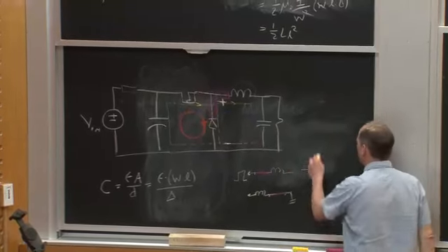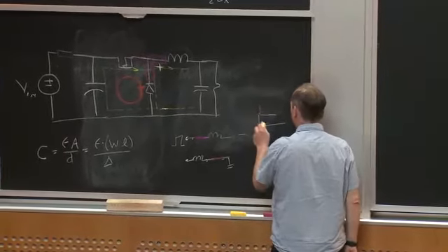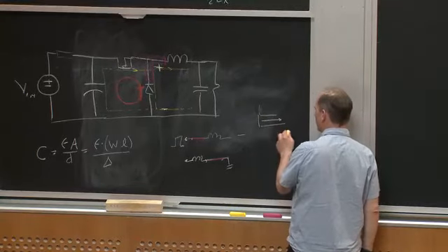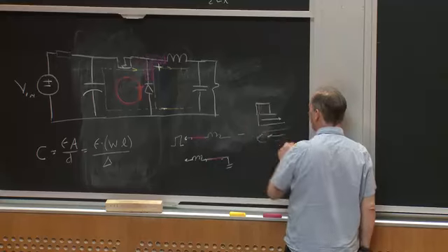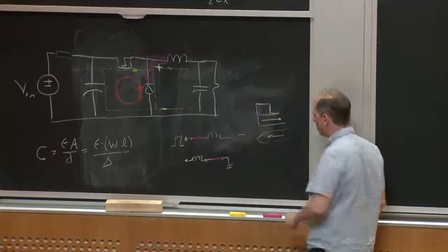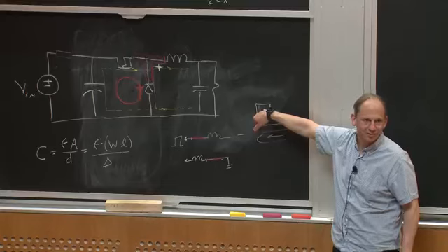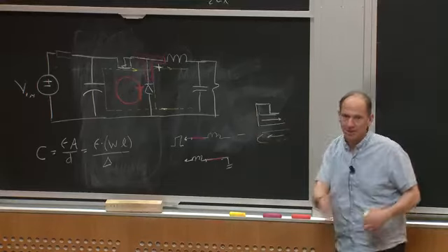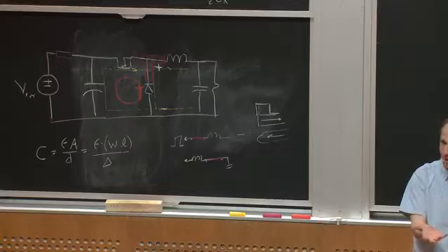If I'm going to carry some current over some distance, it's going to return underneath here. If I put some piece of metal out here that doesn't really carry any current, it can add capacitance without reducing inductance. So I can certainly do things to make both inductance and capacitance worse, or make one of them worse without helping the other.